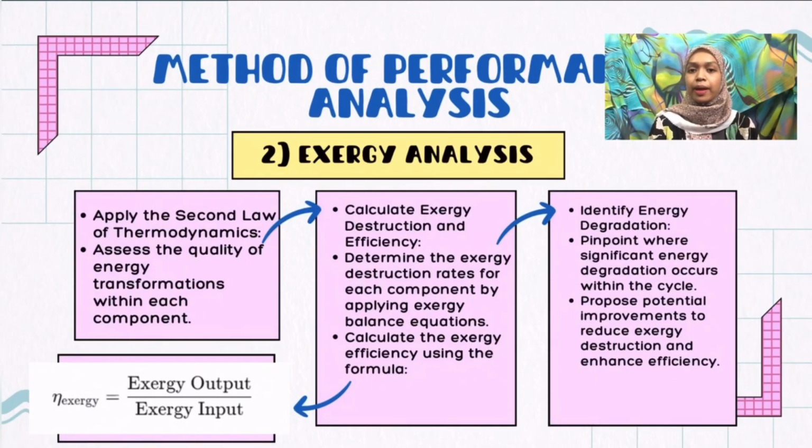First, we need to apply the second law of thermodynamics, to assess the quality of energy transformation within each component. Then we need to calculate exergy destruction and efficiency. Determine the exergy destruction rate for each component by applying the exergy balance equation.